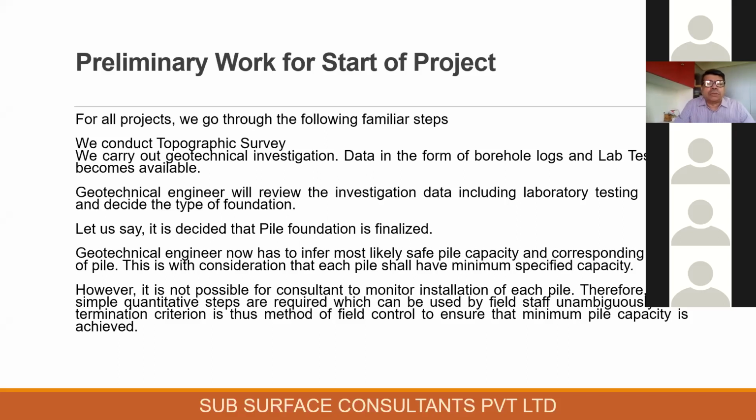Once the pile foundation is finalized, that is, the choice is not there and we must go for pile foundation, the geotechnical engineer has to decide, using the data, the most likely safe pile capacity, and to achieve that capacity, what length of pile he must provide or design.